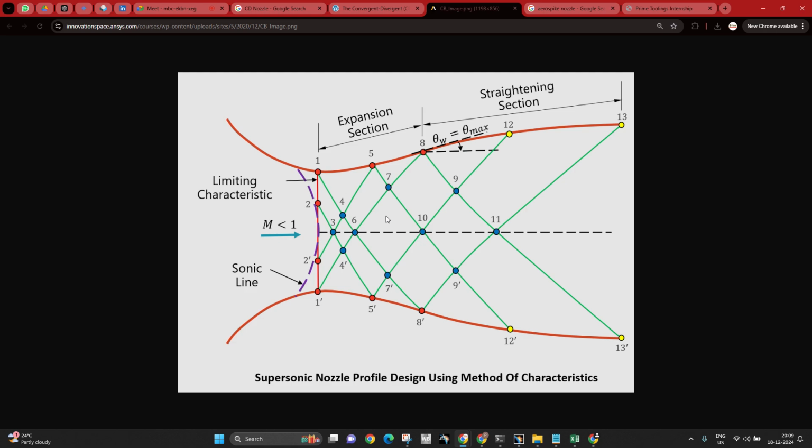You might be assuming that the pressure drop goes from 100% over here to 0% as it goes outside. No, absolutely not. It will be somewhere around 60% or 70% pressure, just a 30 to 40% drop, because you need some sort of pressure recovery system in order to get a smooth stabilized flow at varying angle of attack or varying atmospheric pressure, because you need to consider the environmental pressure as well.